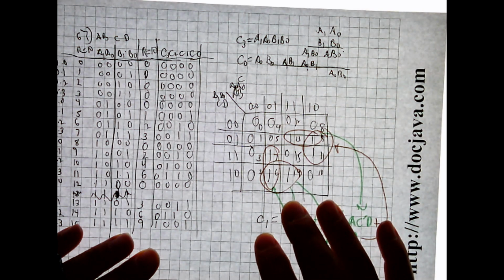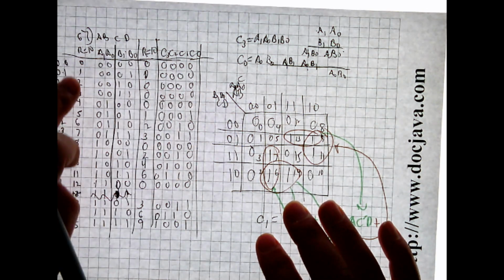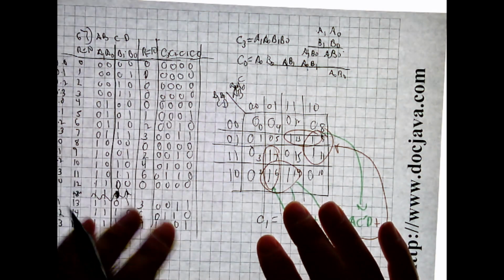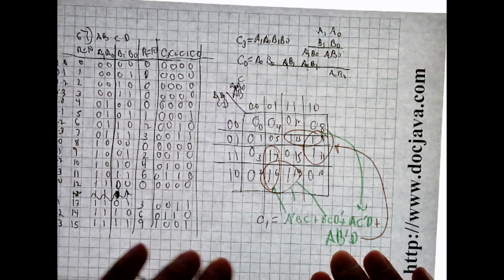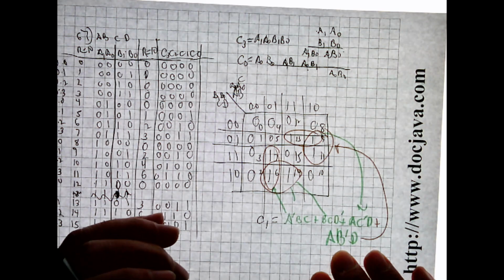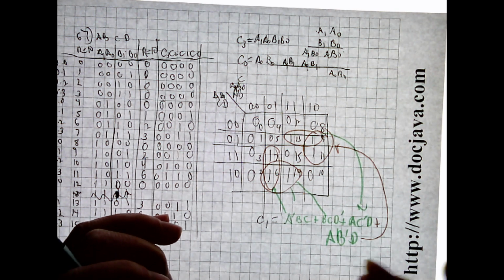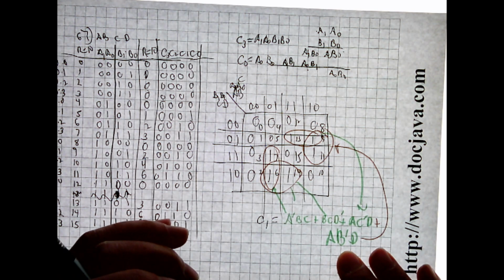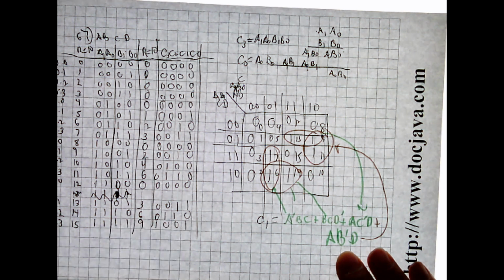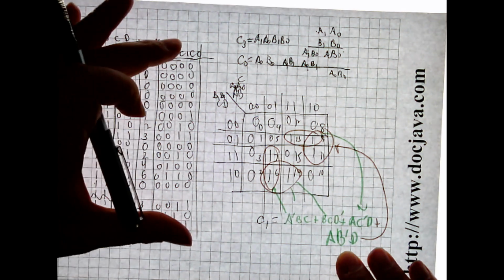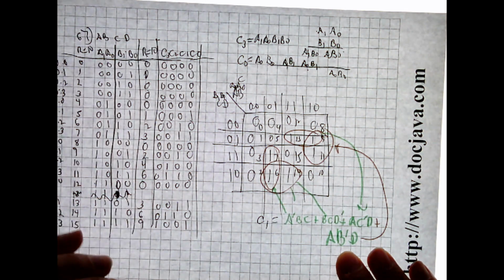But maybe the easiest thing to do is just to do it as I've done, writing out the truth table, getting your minimum sum of products form, and then seeing if you can match that form, or match the canonical form if you like, with the gates that you see in the schematic. Actually, matching the canonical form with the gates that you see in the schematic is basically the same thing as trying to match the truth table.